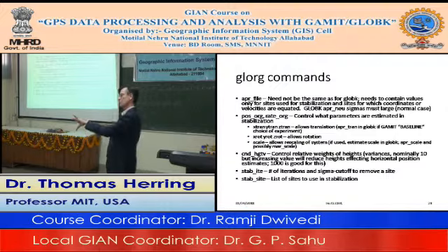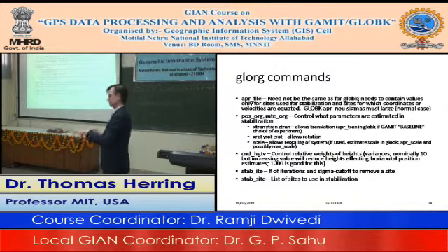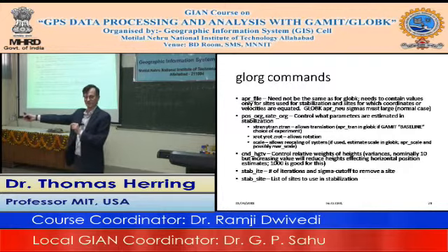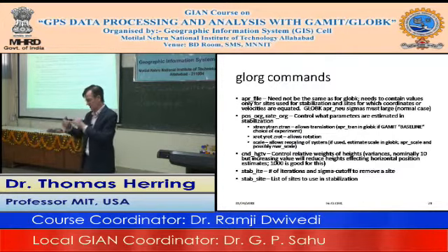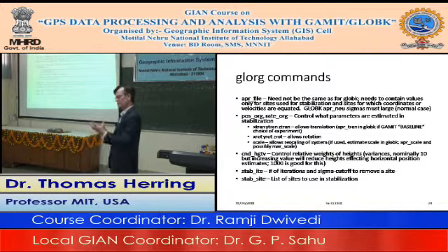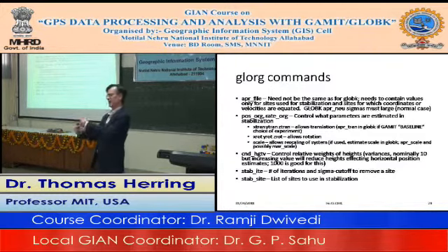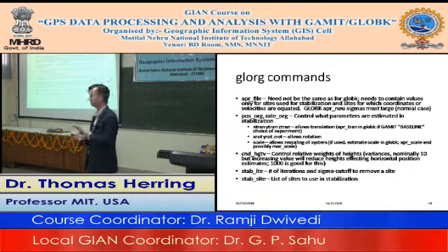Now, in doing that rotation onto the reference frame, there is an issue about what weight you want to give to the heights. Now, as I said, heights have a bad habit of being influenced by loading. So you might have a station that's moving nice and linearly, horizontally, or as a function of time, but its height's going up and down with a strong annual signal. And so if you don't take into account that height variation and you try to reorient your reference frame, there will be some bias in the reference frame associated with doing that.